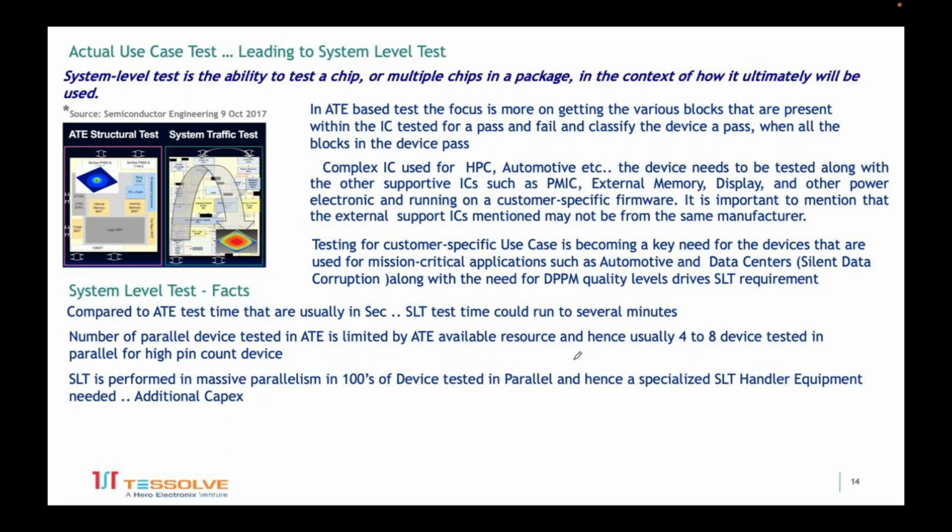Jürgen, Mike here. Just another quick comment as well. That's the reason we do a known good die flow, so that by the time you get to system level test, you're fairly confident in all the die and all the packaging that's gone on in advance.